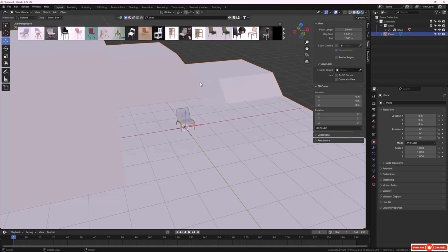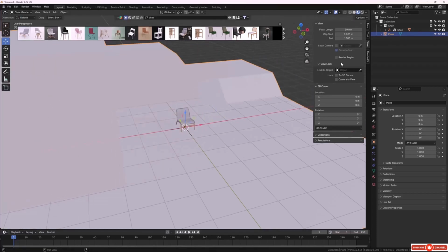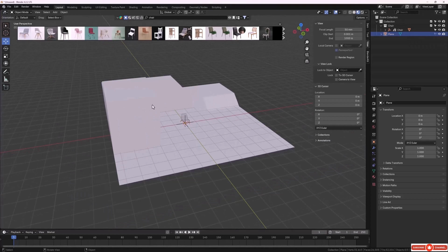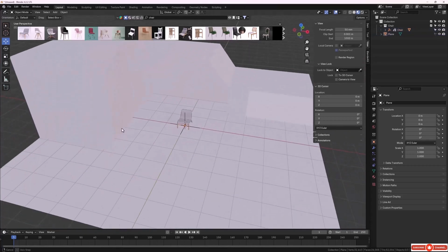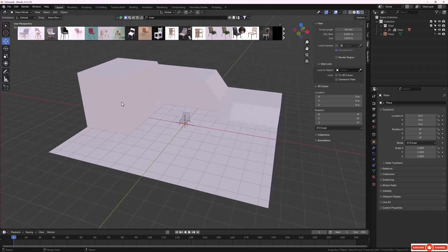So this here, what's this? This is the plane, and as you can see, I can move this plane. Now, if I actually just click on this arrow that we've just brought in on this plane, now I can no longer select this plane. I can no longer accidentally move it around. So that is absolutely brilliant, so that when we are creating our house, once we've built our walls or built our floors or built our roofs, I can't accidentally grab it and move it and not realize that I've done that. So that's why I've brought that in like that.